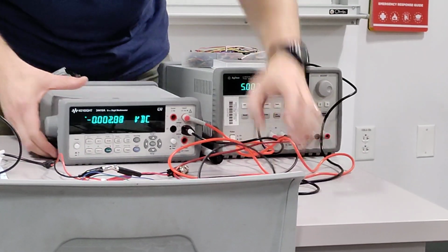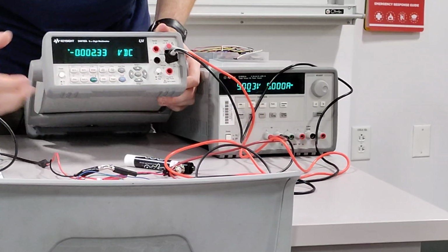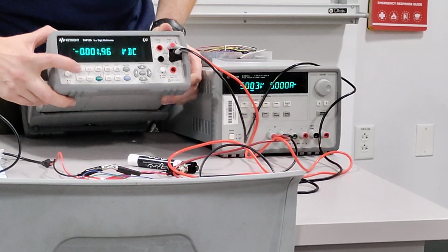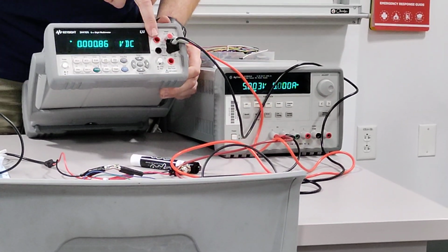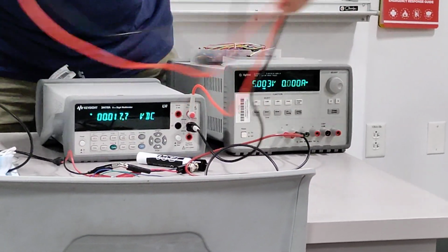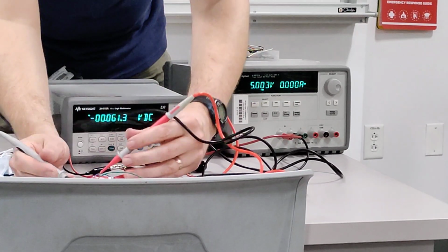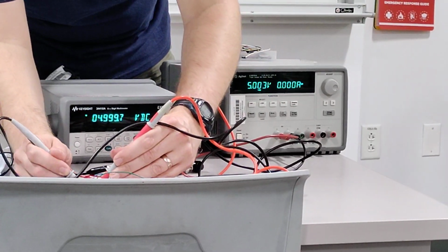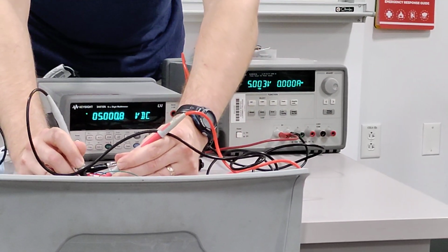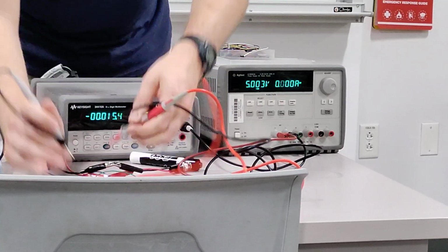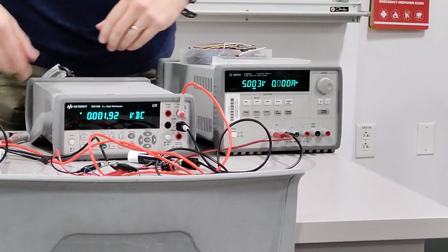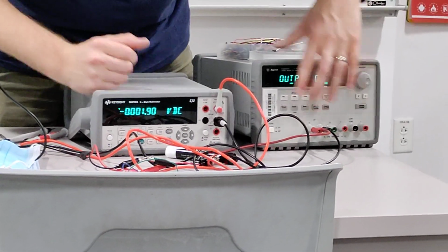So those 2 are hooked up, and then there's, again, loads of buttons on the screen. Right now it's set up to do volts DC, which is what I want. It's this button that says DCV next to it. It says auto range, and so it'll just figure out what I want it to say. We're looking for 5.002, because that's what the power supply says it's doing. And we're getting 4.9968, which is close enough to me. But you can see the multimeter is significantly more accurate than the power supply at telling you what it's actually providing. So, this is a good point, I think, to talk about this breadboard.